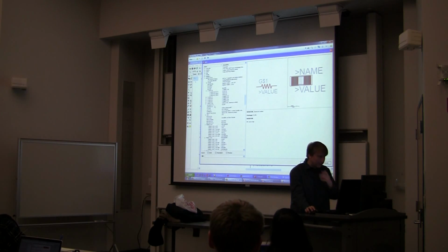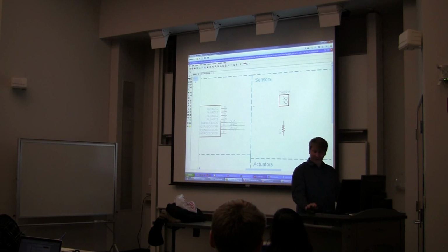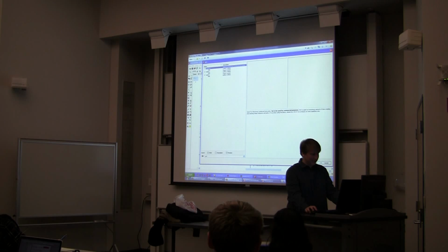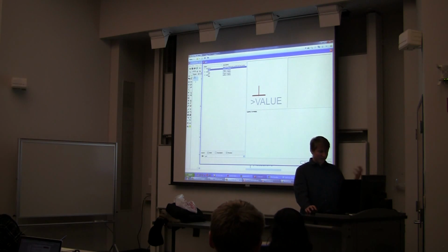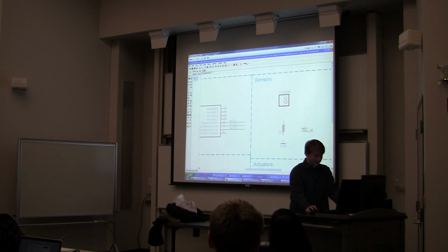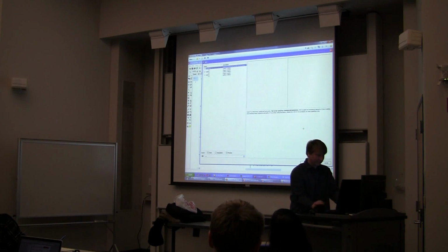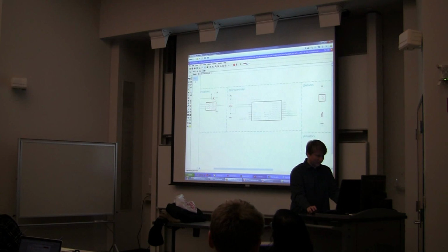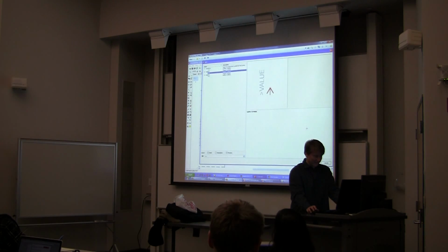I believe those are not in your library, so don't use our library because they're logical symbols. So I'll just type add GND if you remember. There's one in SparkFun, so if you want to use the one that SparkFun copied out of supply one, you're welcome to. I'm just going to use it straight out of supply one. I'll stick the ground there, and then I needed a VCC, which is right there. Now let's just make sure that looks like the VCC over here. Yep. Okay, so now I've got that.